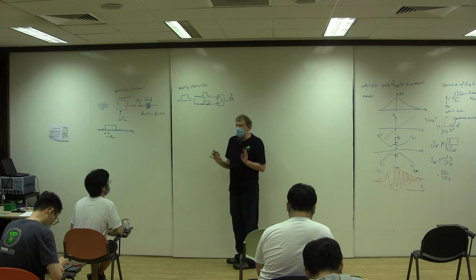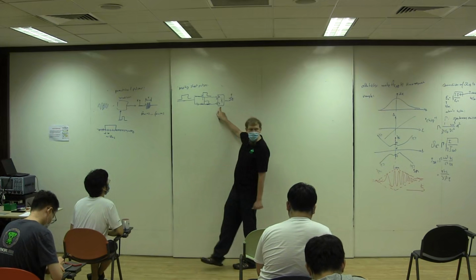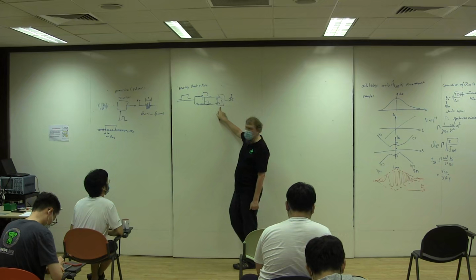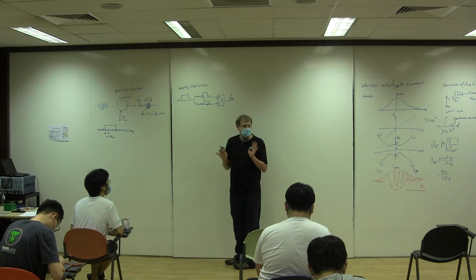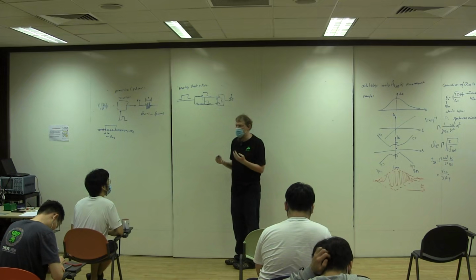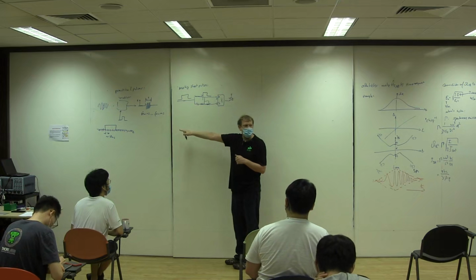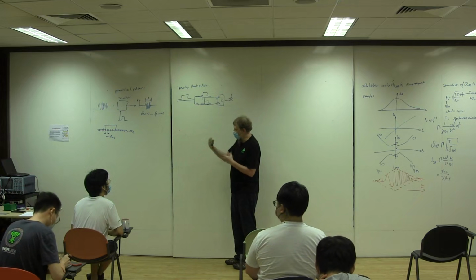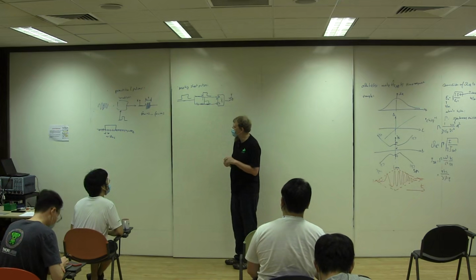You can do this with normal cables usually, as long as you have a fast enough gate that can do this operation. You can play all kinds of funny tricks simply with cables. If you need to make short pulses, and you don't have deep pockets for a generator that has a time resolution in the sub 10 nanosecond range, then you can play with this trick here.